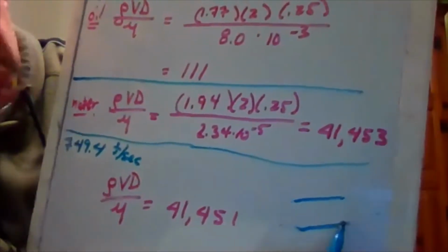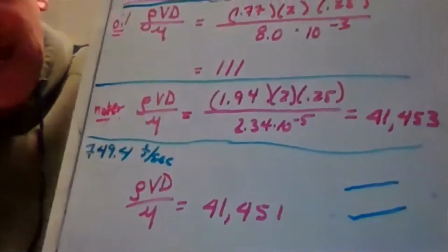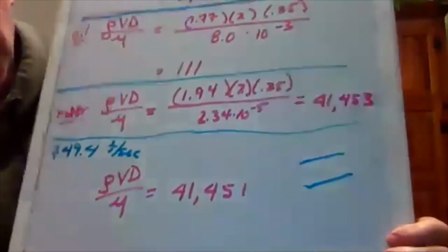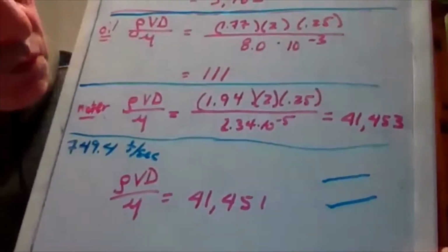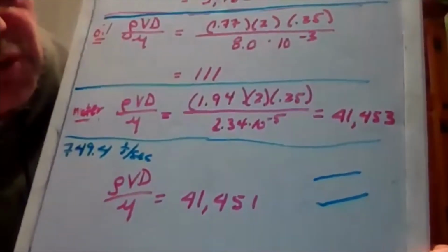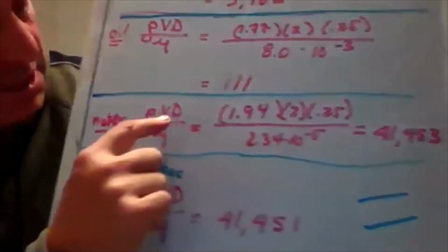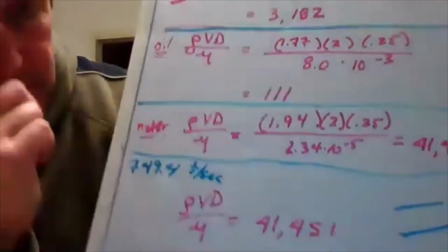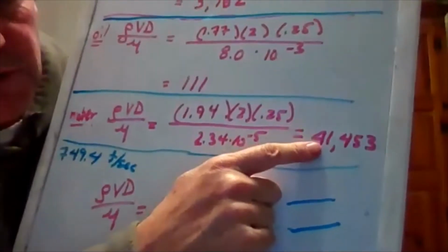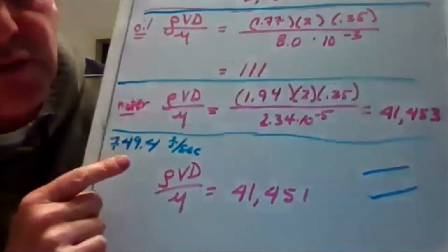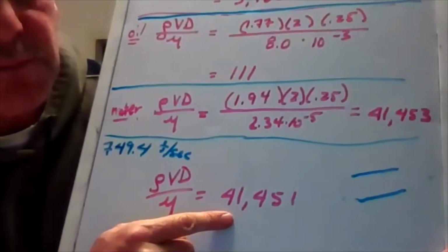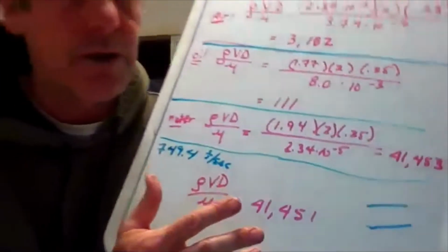So those lines are supposed to represent the side of the pipe, and the look of the flow. So for example, the degree of swirling is determined by the Reynolds number. So we would say in this case, this water at 2 feet per second would have a certain swirling nature, and the swirling nature of this oil, because it has the same Reynolds number, would be the same. All right, so the Reynolds number is telling us the likelihood of turbulence: the higher that Reynolds number is, the likelier the turbulence is, but the number itself also means something.